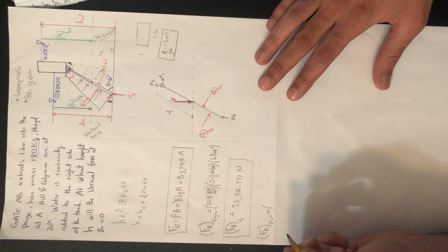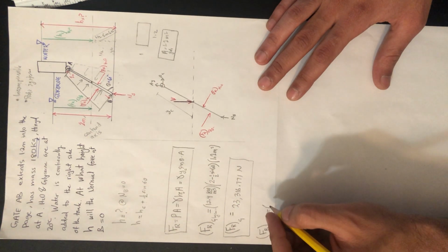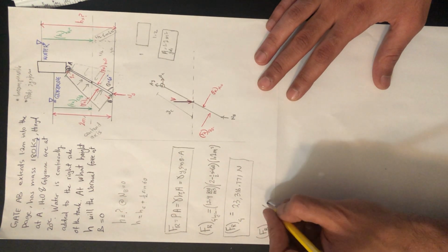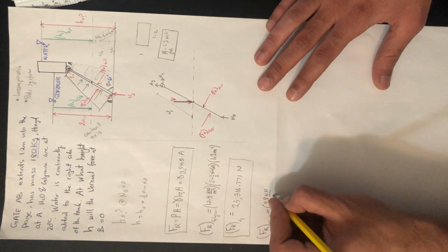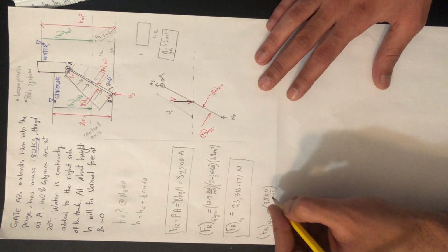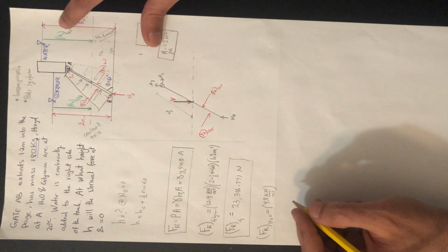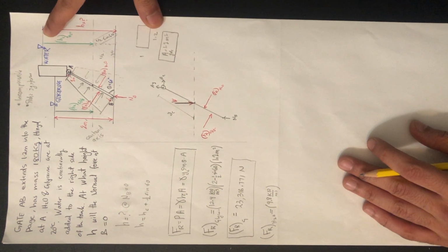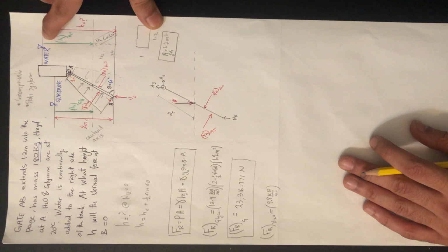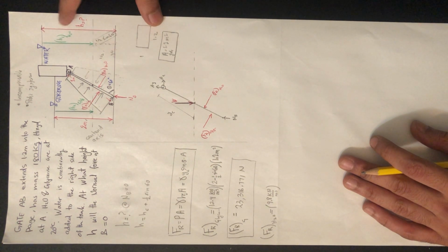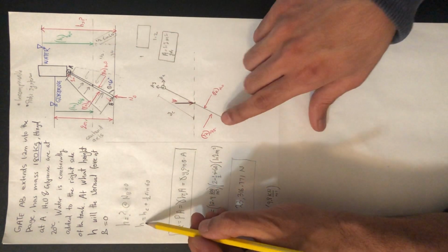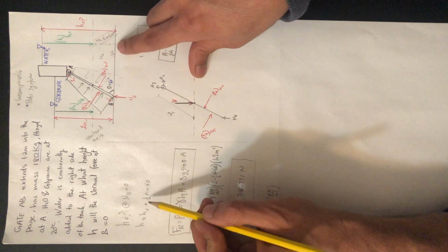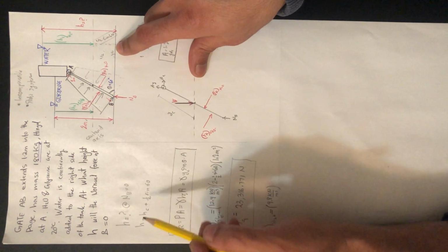and our specific weight from table 1.6 is 9.8 kilonewtons per meter cubed times HC for water, which is going to be H minus the vertical distance. So we did say here H is HC plus the vertical distance.